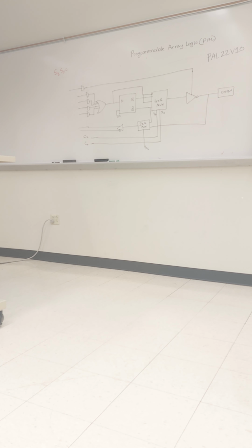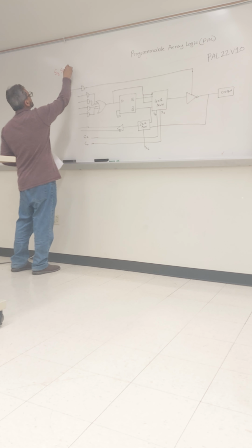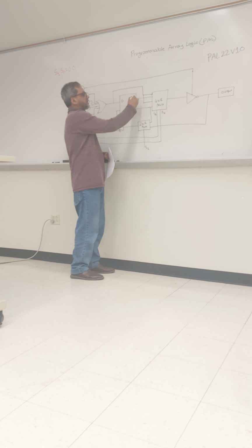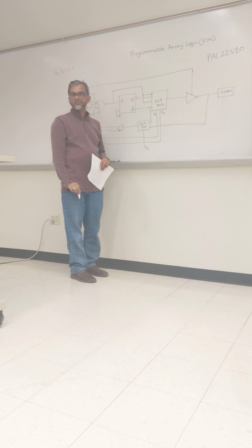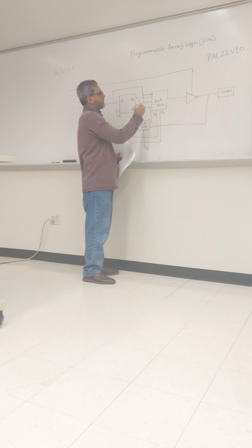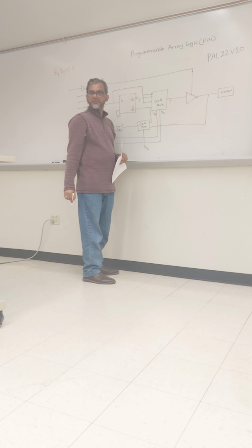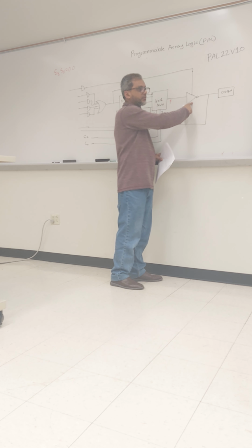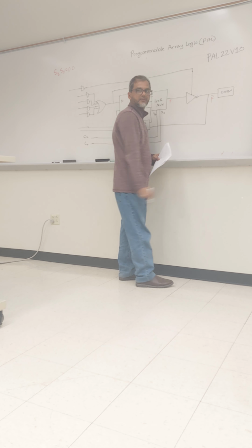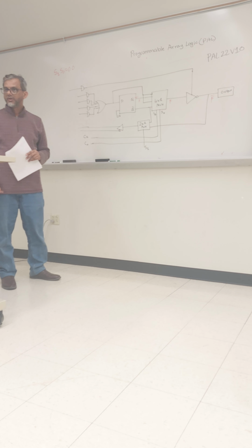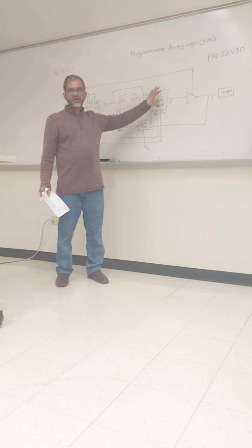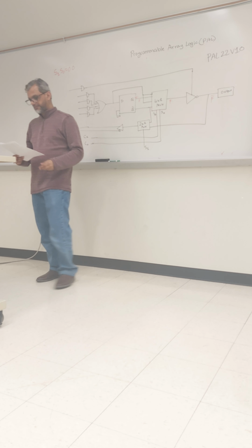When S1 and S0 equal 0, 0, it will select this Q. So if it is Q for F, for example, then it will give F here. Then if the control input is enabled, the tri-state buffer is enabled, it will give you F bar. This is the one function. So that means it is giving you the registered value, right? From the register, it is giving you the information, register function.